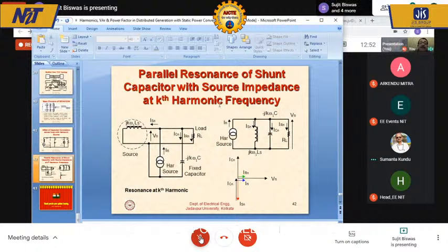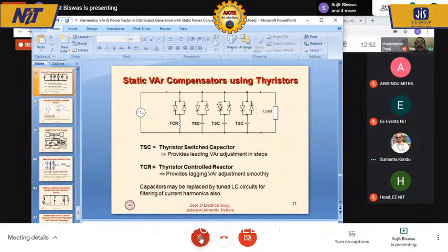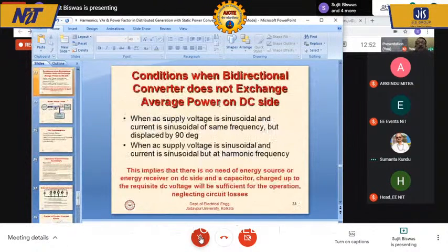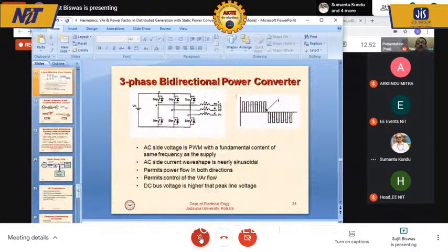So therefore, you cannot connect any capacitor directly onto the line, even if it is for an LC filter. So you have a capacitor here and then put one more inductor on the other side. The objective of putting this inductor is to prevent this capacitor from getting connected in resonant mode with the source reactance. So it's a sort of decoupling from the source. The right-hand side is now the AC source, so it's decoupled from the source.